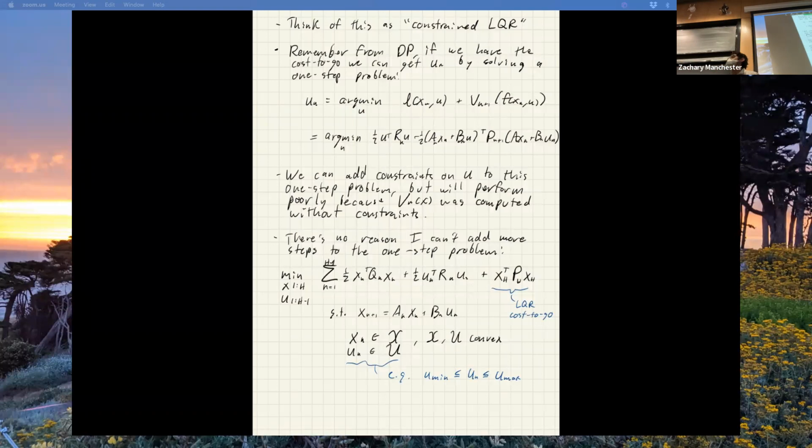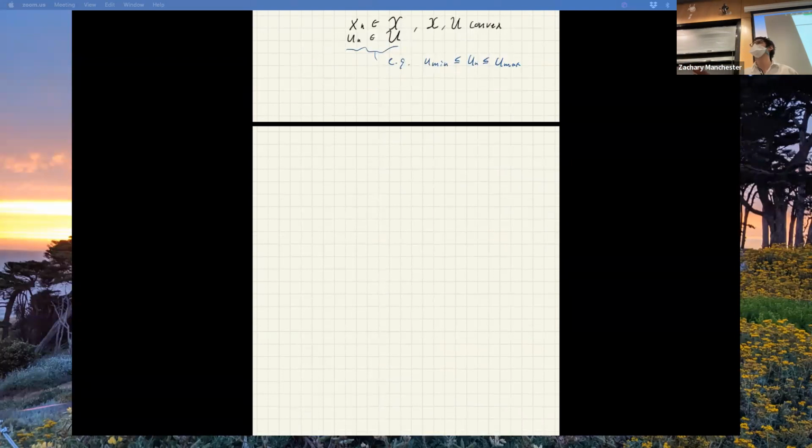So what I can understand is that with the constrained LQR, we just plan everything from the final step, and with the MPC, we go ahead again. So we start backwards and then go forward. Yeah, that's kind of right. In particular, you would be getting this cost to go approximation from a backward Riccati solution, assuming no constraints. And then in the forward setting, you'd be doing this with the constraints in there. I'll talk more about that, but I don't want to get too ahead of ourselves. Is everyone cool? We keep going.